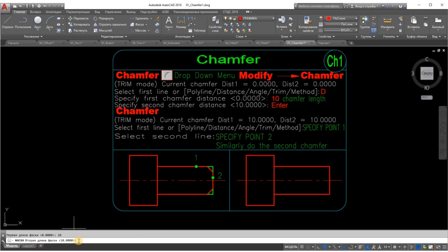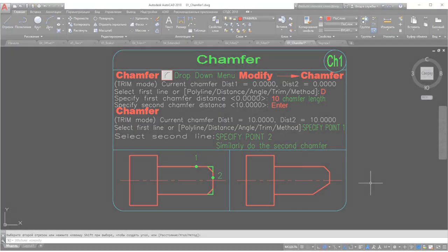You can add fillets to arcs and splines, and you can fillet all the vertices in a polyline at one time by choosing the polyline option before you select the objects. Holding down the Shift key before picking the second line automatically gives you a clean intersection, the same as if you had set the fillet radius to 0. The chamfer command has the same Shift selection option.